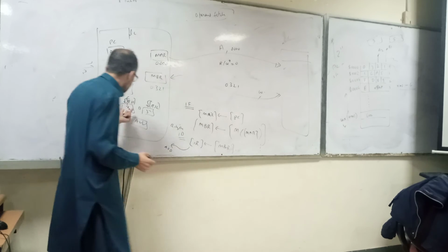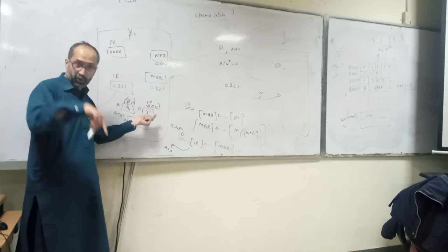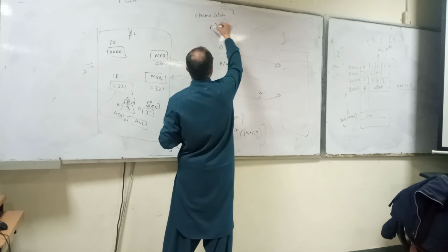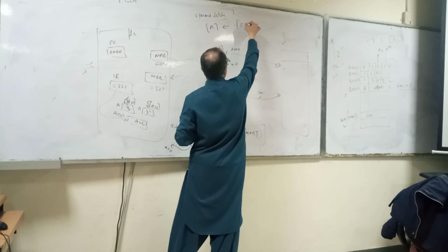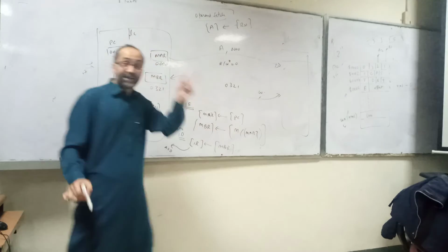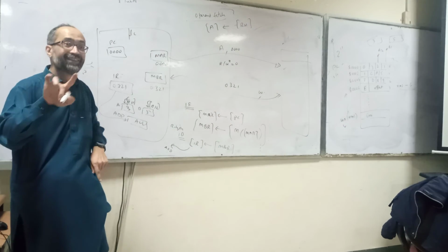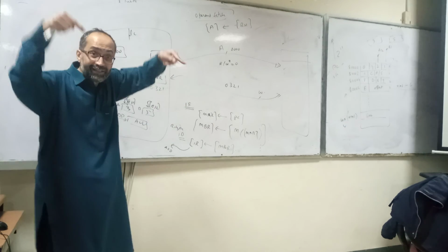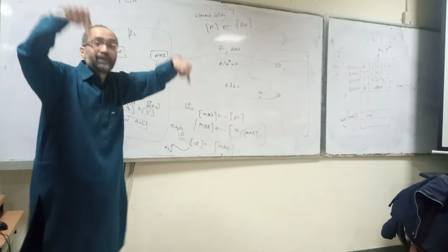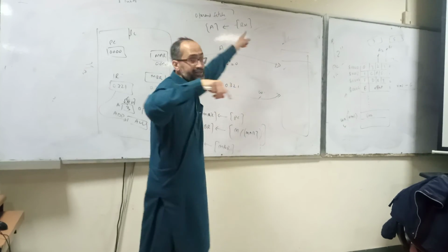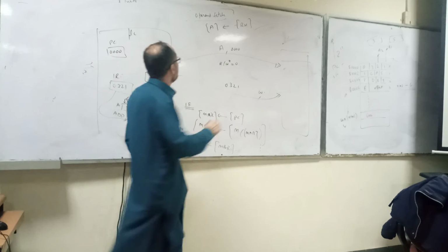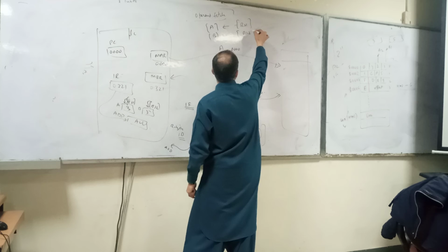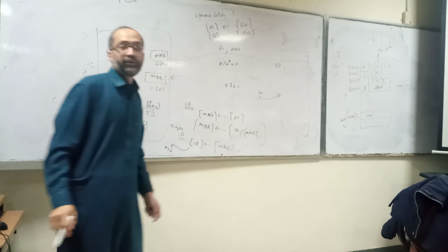So in the operand fetch stage, we assume that there are two temporary registers A and B within the microprocessor that are attached to the ALU. What will be updated in A? The contents of RS1, not RS1 itself, because RS1 is a 4-bit field. The contents of RS1 means the contents of that register, and if we assume that register is 16 bits, it is a 16-bit value. Then B will be loaded with the contents of RS2. This is the operand fetch stage.